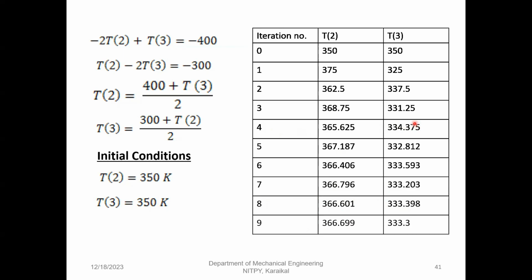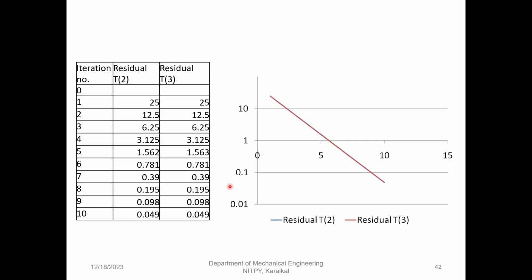For this case it's not varying much, but in real life, the solution may not be as good as the physical solution. Now this difference between the previous time step and this time step is called a residual. Fluent generally checks whether the residual is decreasing. If the residuals are decreasing and come below something like 10 power minus 6 or minus 7, it can say the solution has converged.